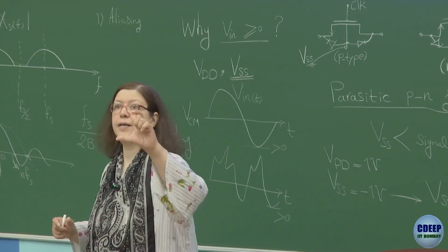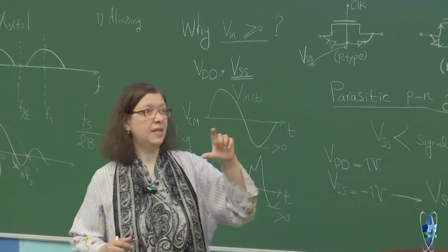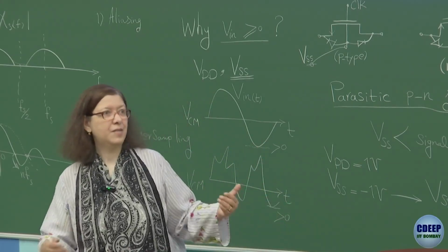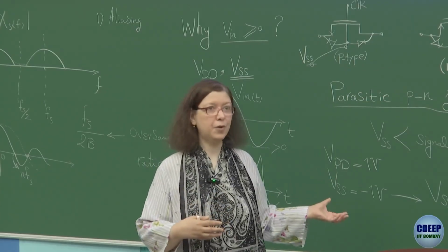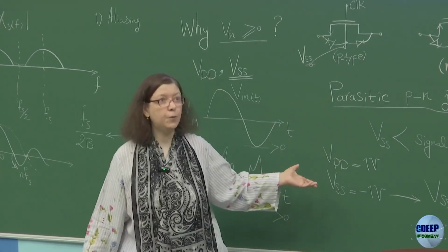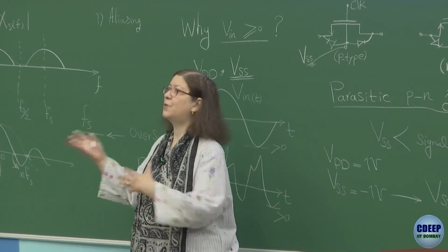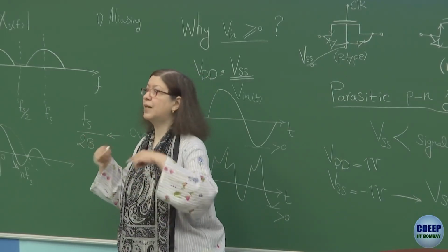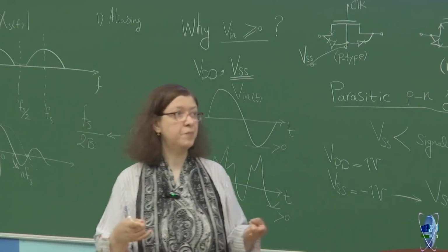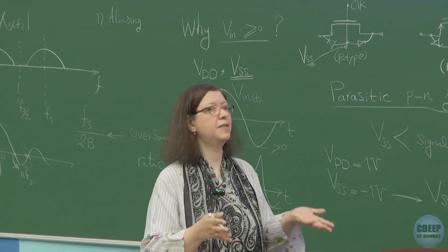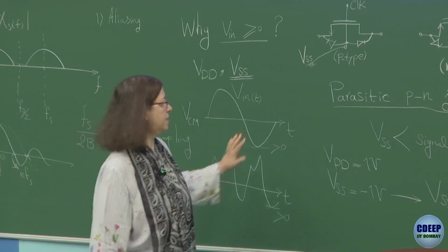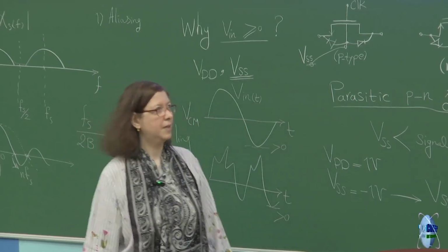These are devices with a higher oxide thickness, which are called thick oxide devices. Those thick oxide devices naturally don't have, for example, the current drive capability of core devices, but still they are available. And in fact, you can find designs at 1.8 volt in 40 nanometer, because they use those devices. So there is in fact more than one type of transistor available. What I am talking about in the class for now is the core regular devices of any technology, which are bound to the supply. Now is that clear? So that was the reason I put these conditions. Okay.